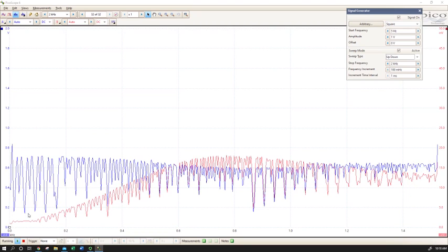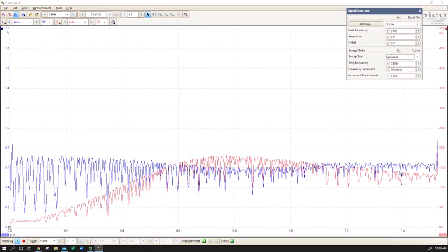Definitely at very low frequencies, I have almost no voltage drop over my resistor. Well, that's because it's all dropping over the capacitor, which is acting like an open as I'm down here at my practically DC frequencies. And then as I go to higher frequencies, I again see the voltage drop over the resistor decreasing, but not as fast. So you can see that the inductor is not responding as quickly to frequency as the capacitor, so that might tell us something about its relative value.